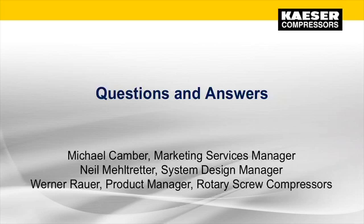And Michael, it looks like we're back to you for this question. How often should we inspect our piping for buildup? Well, a key predictive maintenance plan might include an annual inspection of the piping system at key points, but what you really want to look for are indications that there's a problem.